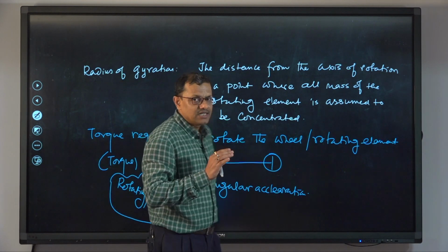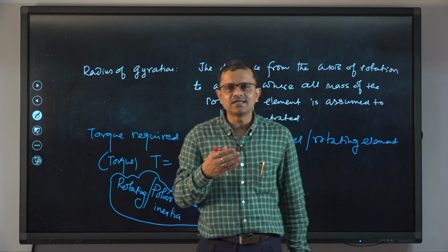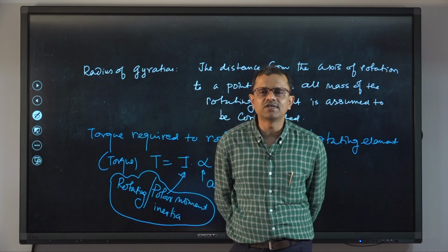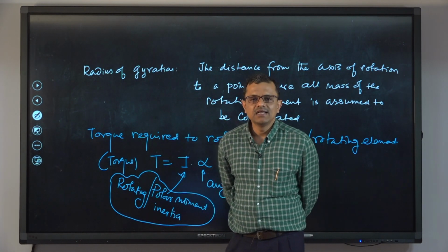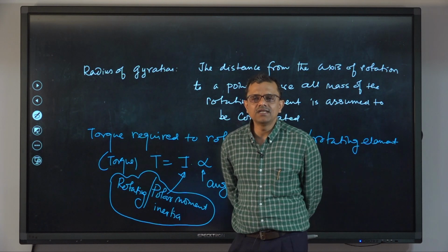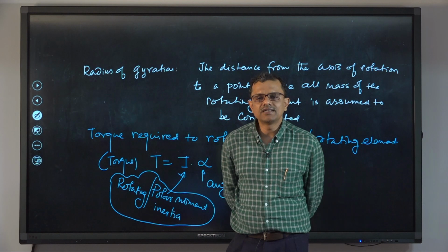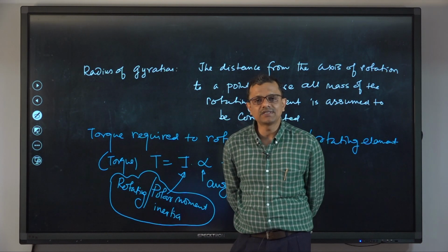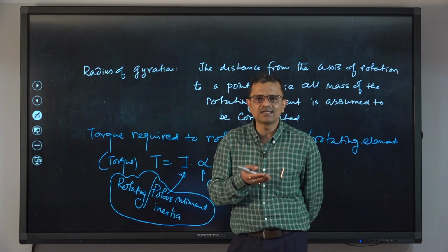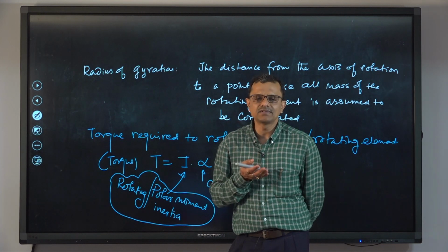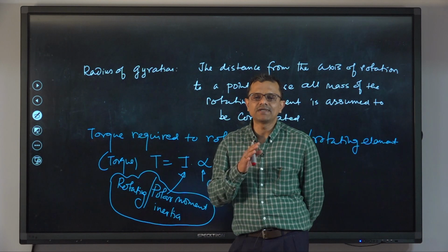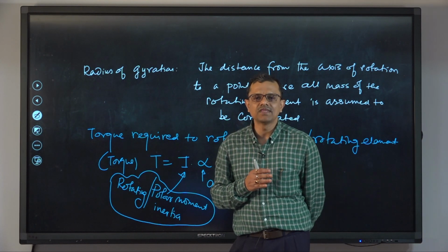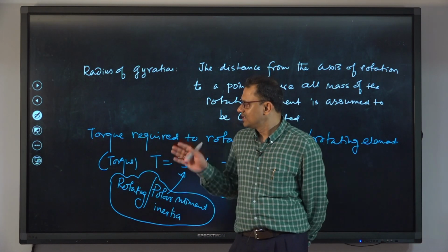Okay. But the question is, whenever someone considers lightweight ceramic material for the construction or fabrication of the turbine runner, he or she must be thinking about a material that will be able to withstand high pressure and high temperature, because exhaust gases carry enthalpy, and they have high pressure and high temperature. So, the material must withstand that particular thermodynamical condition without any mechanical failure.